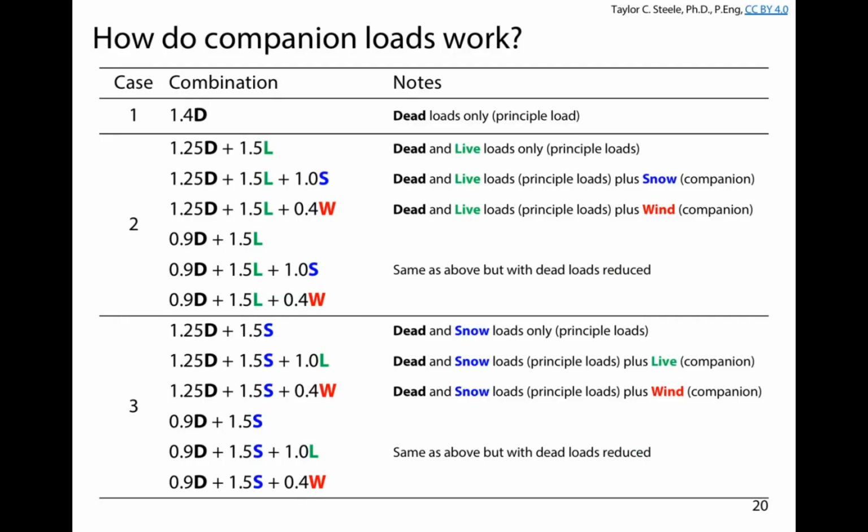That seems weird. Like, let's reduce the amount of weight of our building. It means let's underestimate the load of our building just in case something bad might happen if we do that. What might happen if we calculate a dead load and the weight of the building's less? Is there anything that could happen to our structure in that situation? What if wind is blowing on our structure?